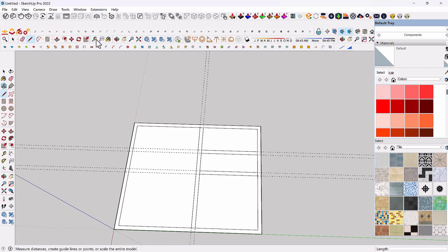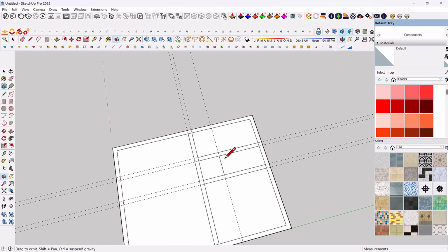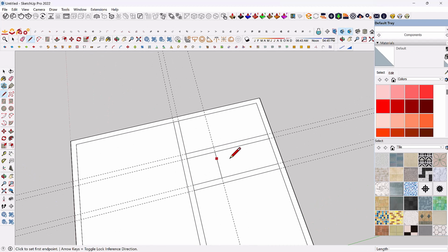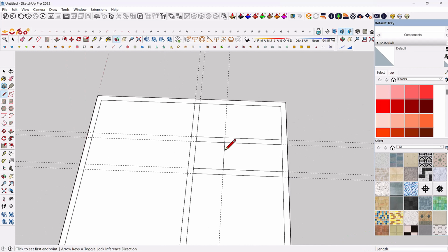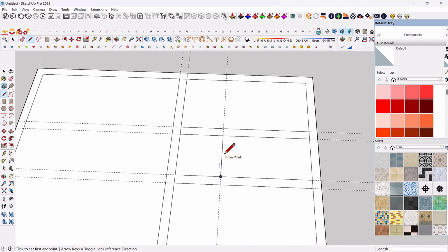So what I'm going to do now, I'm going to pick the tape tools and measure 1,200, enter. Then I'm going to pick a line tools and trace it. For this part, we are going to use 150 block. This time around, we are no longer using 225. So we're going to use a 6 inches block.